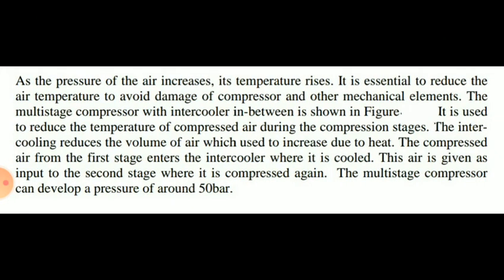As the pressure of air increases, its temperature rises. So it is essential to reduce the air temperature to avoid damage of the compressor and other mechanical elements. The multistage compressor with intercooler in between the two stages, as shown in the figure, is used to reduce the temperature of compressed air during the compression stages.